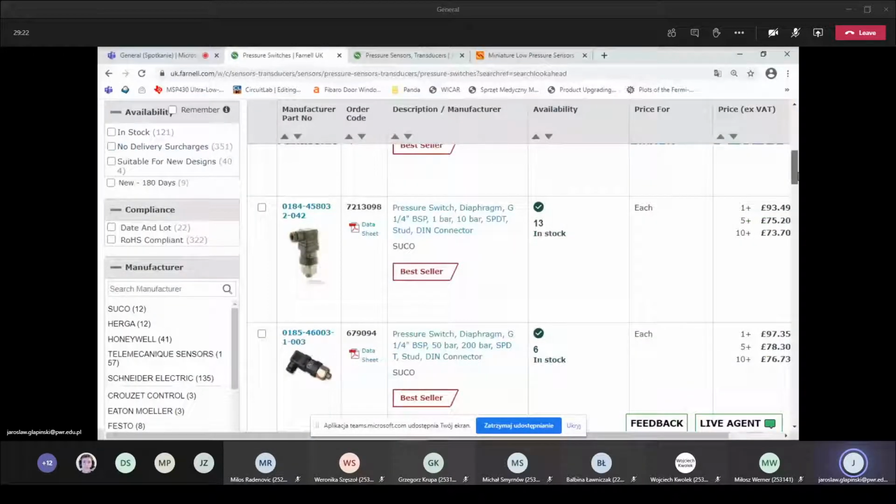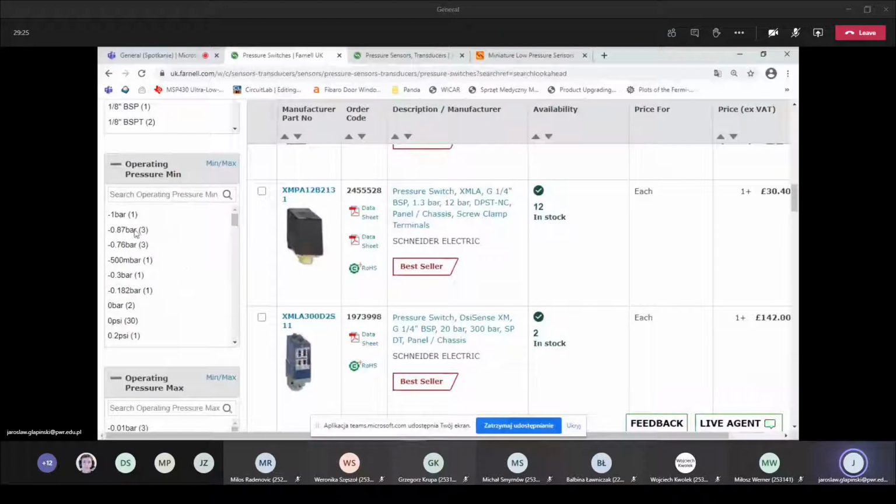So we can sense pressures below the atmospheric pressure and above. I would like to notice that we have no pressure below 0 bar absolute. So we have no pressure below 0 atmospheres, because sometimes some students can say that we've got pipes, for example, that we can use the pressure minus and plus 5 bars. So you remember that we have no pressure below absolute 0. So we rather measure some pressures above the atmospheric pressure.